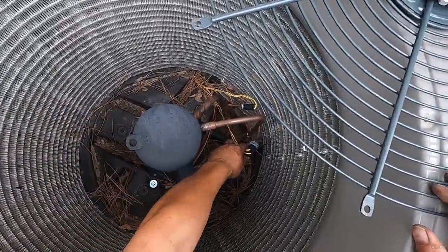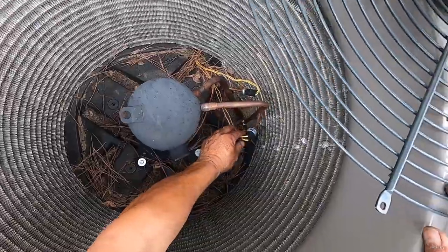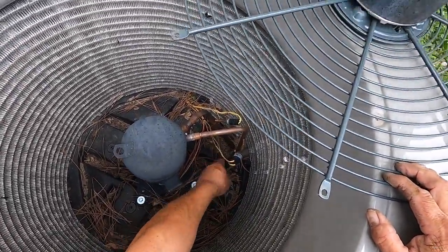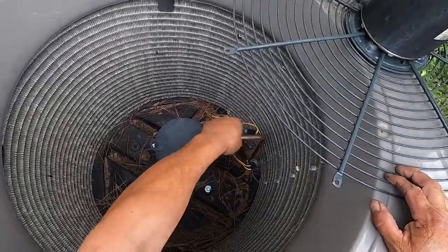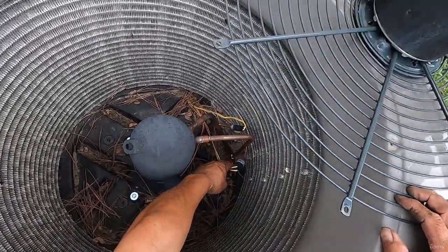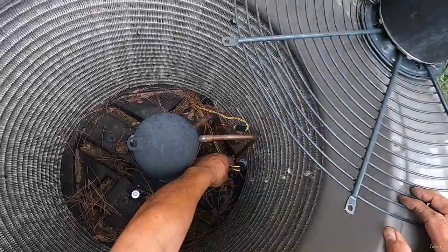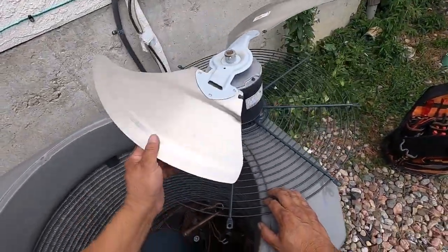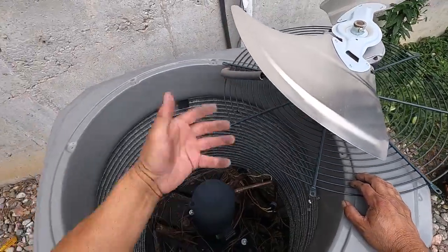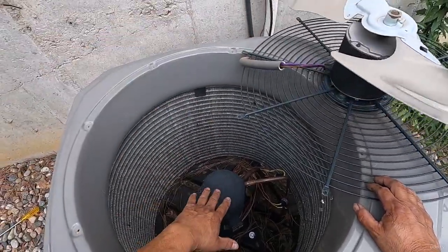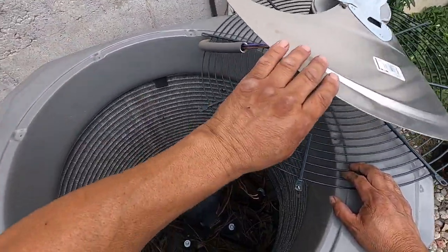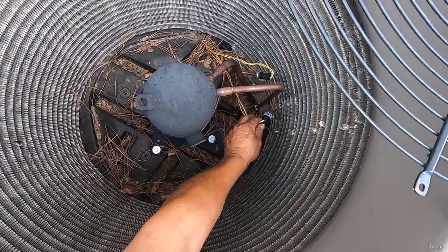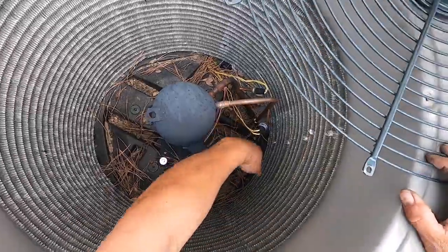And these here are pressure switches, and you have one on the high side. So for example, what will happen, and these are connected to the contactor inside, and we'll show you that after a while. But these are if the pressure gets too high, so for example, if the fan motor goes out or seizes, it's not able to get rid of that heat, and the pressure is just going to rise and rise and rise because it's not getting rid of that heat. And this will open. It's a safety device for the compressor to protect the compressor.